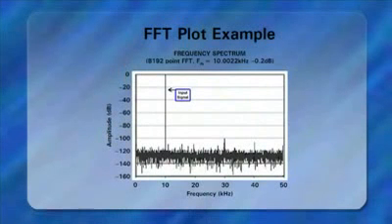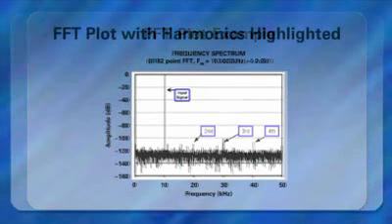In the past, FFTs were difficult to obtain because of the available computing power. This environment made ENOB numbers very valuable. Now FFTs are much easier to generate, which reduces the importance of the ENOB specification. If you view the data in the frequency domain, you can compare the input signal energy to the energy that's spread around all of the other frequency bins.